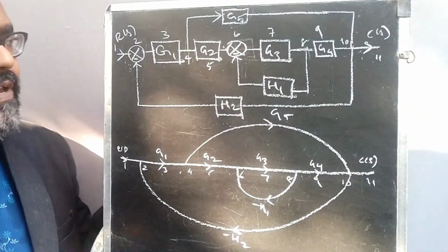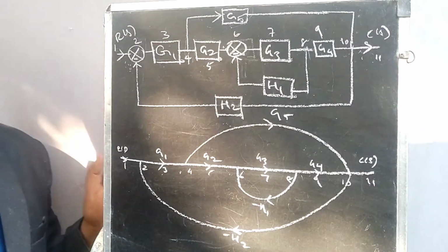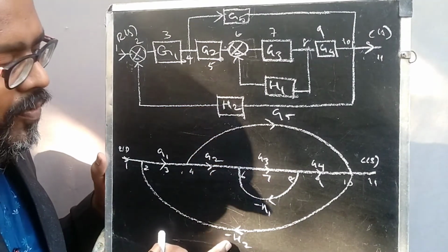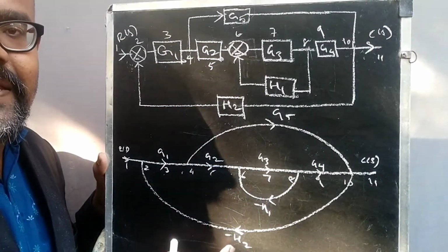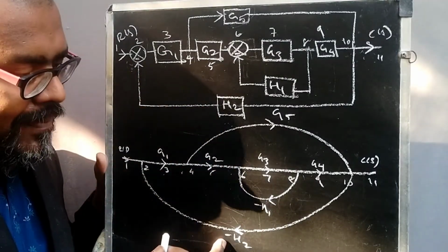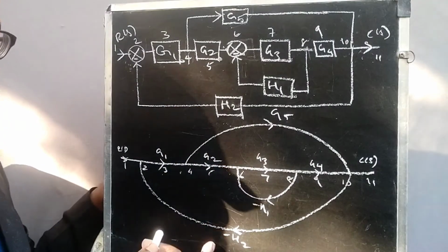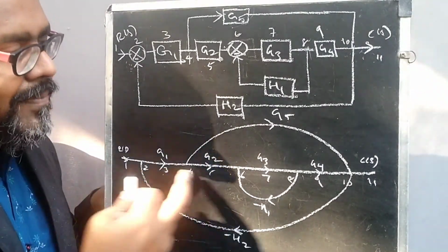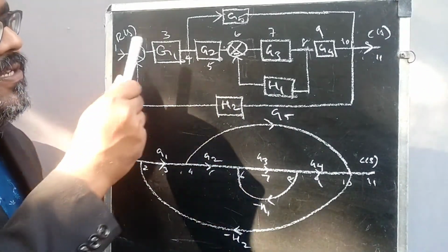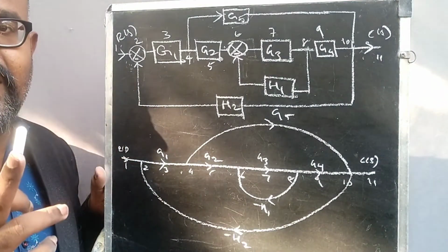That's all. We are just converting this particular block diagram into the signal flow graph successfully. Okay, most important thing is you need to put minus sign here. If in the summing point you are getting the negative feedback path, then the minus indication is very important. Most of them make a mistake right here. Please number properly, and the connection made is very important, because 2 to 10 and 10 to 2, that word makes a difference.